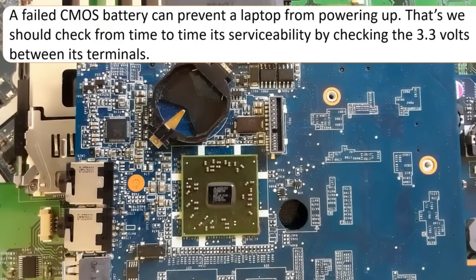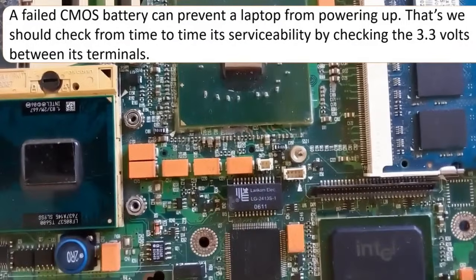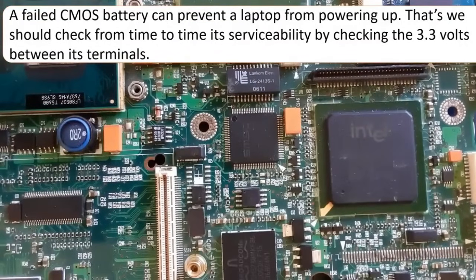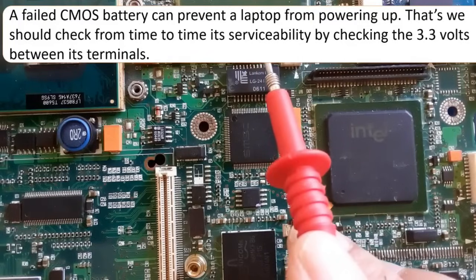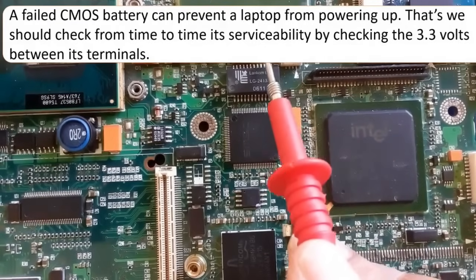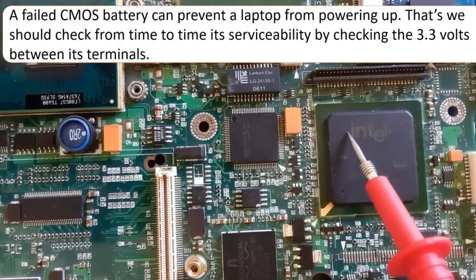Always you will find the CMOS battery near to the ICH, and the ICH is always near to the SIO and the BIOS chip. This is a good information. As you can see here, this is the connector for the CMOS battery. The CMOS battery for this motherboard is removed. So this is the connector.